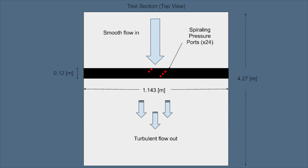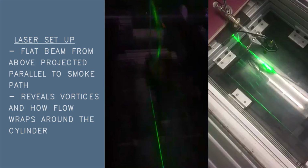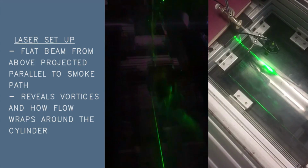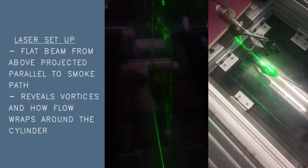The cylinder itself was fixed in the center of the wind tunnel test section, midway between ceiling and floor, as shown. To better visualize flow, a smoke machine was used at the test section inlet to better indicate turbulence and vortex shedding downstream of the cylinder. This was accompanied by a green laser array that illuminates the smoke and blackout curtains that prevent obscuration by ambient sunlight.